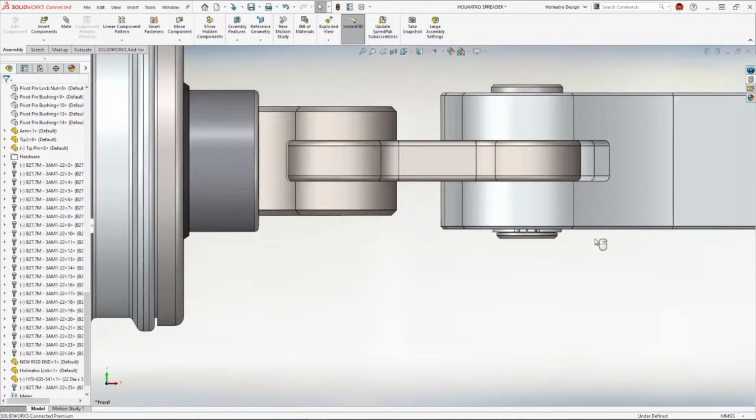Yeah, that's pretty cool. But that was just one pin, John. I think I see a couple more holes there. Are you going to have to do this whole thing again? You know, I would think that might be an issue, but here's the thing. All Eric has to do is just give it a simple window select. And again, he's going to pull up his mouse gestures. As we said before, they're going to be completely different now. He's going to use a copy with mates tool.